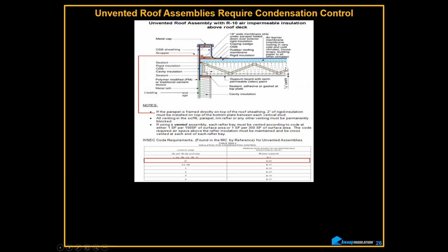It's condensation control. That's all it is. Yeah, you're getting R value out of it. The main reason is condensation control, and it's dealt with by climate zone. So where we are, R10. But if you're in Alaska, you need R30. That's just on the top of the roof. That's not what you need in the roof system. You might need an R60. So you can do 30 and 30, or whatever, however you decide to split it.